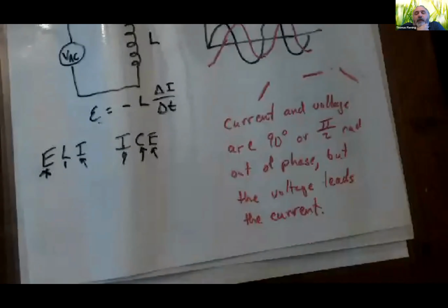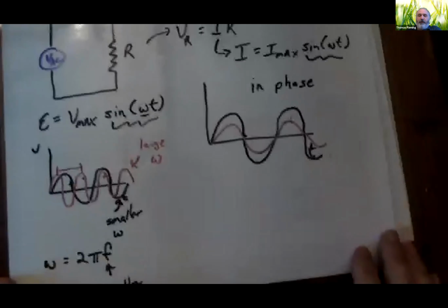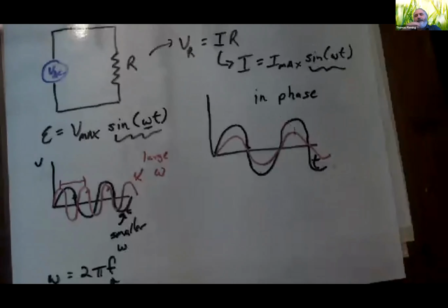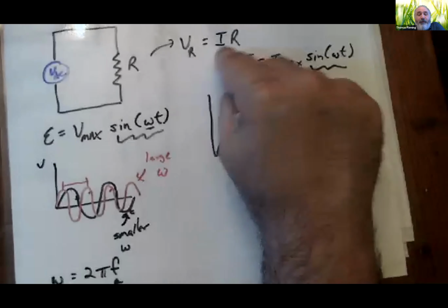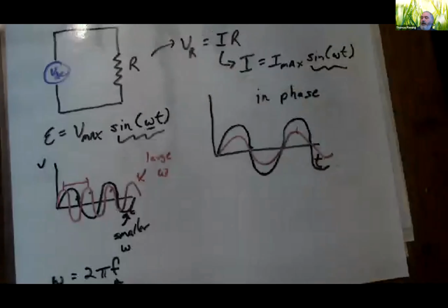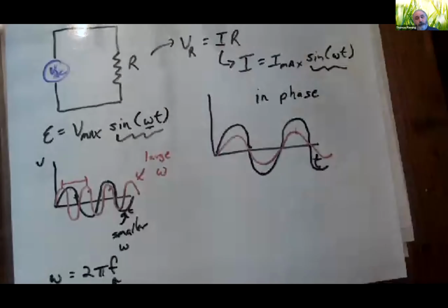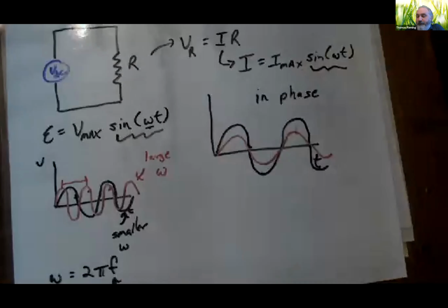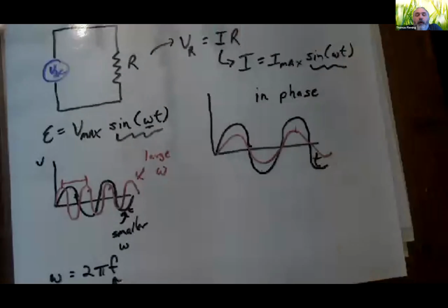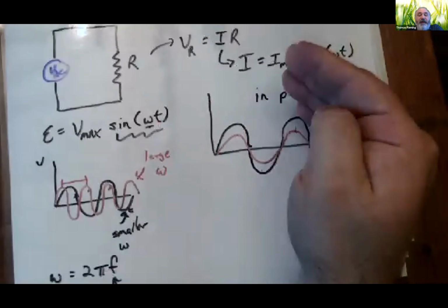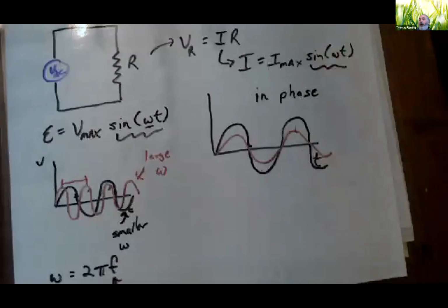But what we haven't figured out is the sizing thing, like how big are these voltage drops going to be? If we go back to the resistor, we know that resistors obey Ohm's law, right? V equals I times R. So the voltage drop across the resistor gets bigger with the current. Cool. And that's similarly true for an AC circuit. It's going to work just as well for an AC circuit as it does for a DC circuit. And Ohm's law is super easy to use.